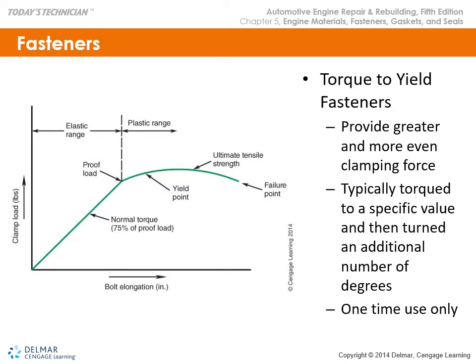Okay, yield. There's a certain amount of strength and clamping force when we do cylinder heads and we do torque critical components like connecting rod bearing caps, main bearing caps, and cylinder heads. We have very precise amount of clamping forces required.